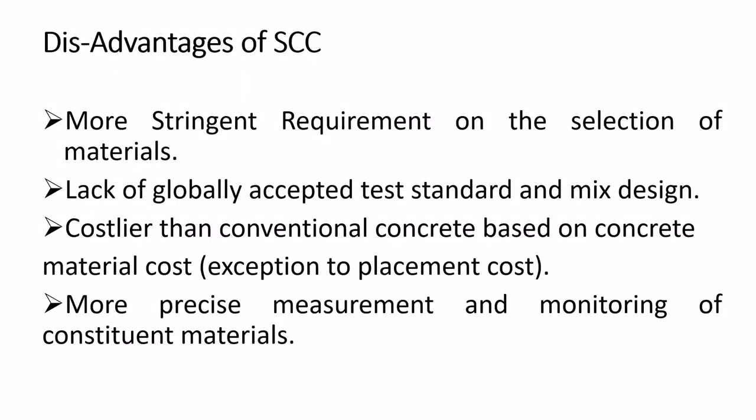The disadvantages of self-compacting concrete are more stringent requirements on selection of the materials, lack of globally accepted test standards and mix design, it is costlier than conventional concrete based on concrete material cost, except for placement cost, and more precise measurement and monitoring of constituent materials.